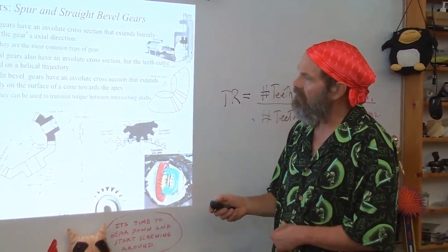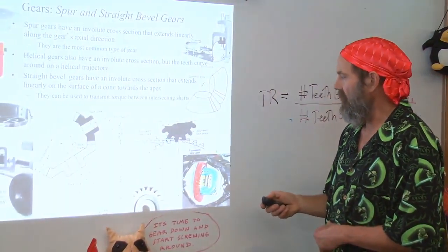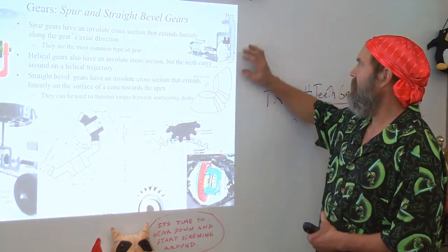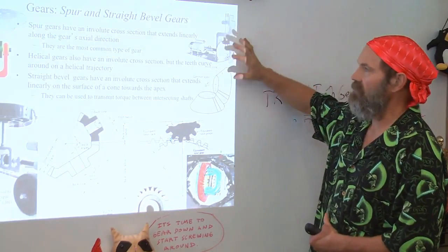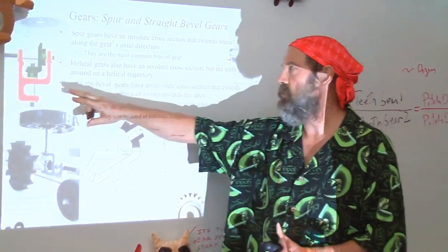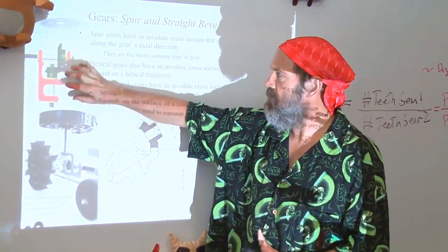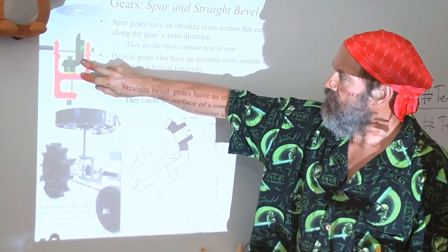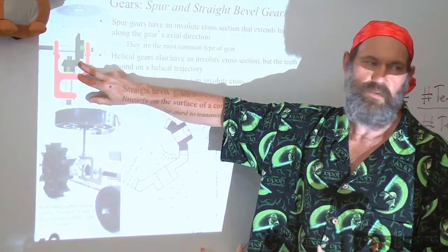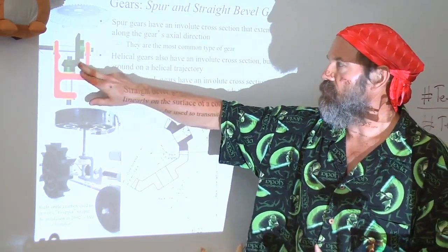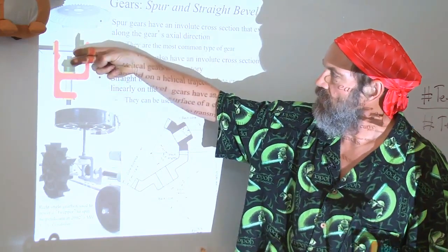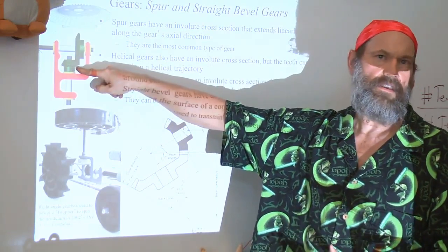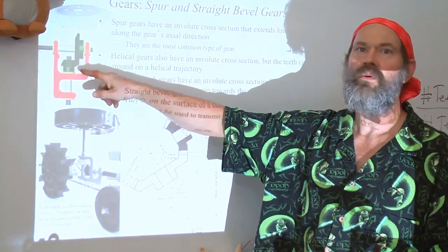Okay? It's amazing how many times you'll find, and these are design examples, not necessarily good ones, that I've pulled off from what other people have done in the past that show the hub, the gear, where the teeth engage, far away from the main bearing. This is such a common problem. It's one of the reasons I keep showing it, is you don't want to do that. There's no reason why this can't be reversed and the support bearing right up behind the back of the gear. Okay? Really, really important.